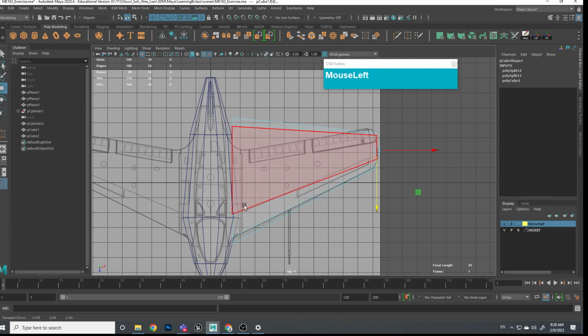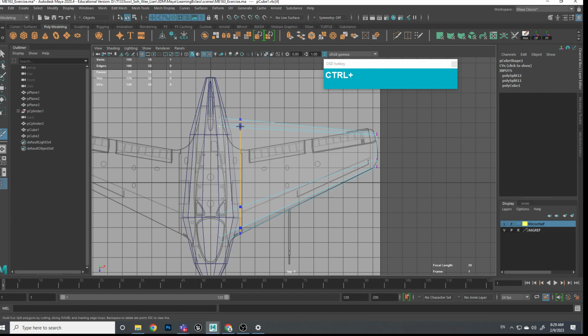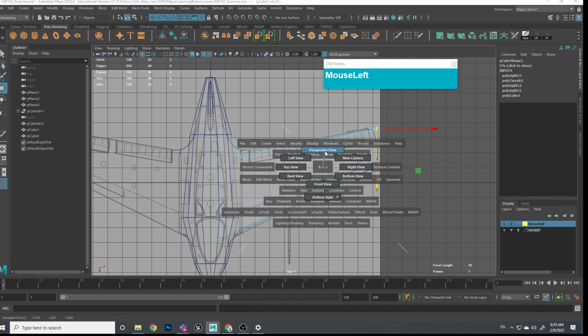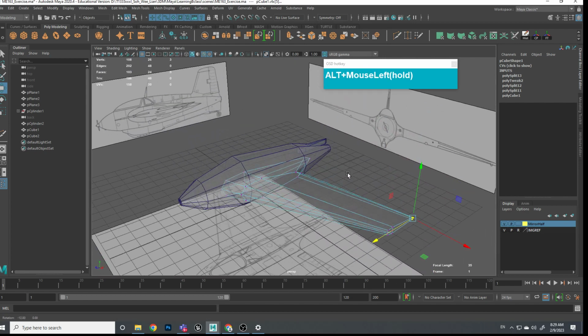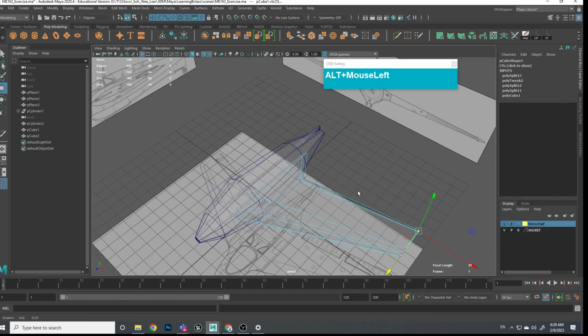What about this area here? We first move the root of the wing until it intersects the body, until it cuts into the body. Then we can insert one edge loop here, right where there's a transition, where there's this curve here. Press Q to select, grab this tail vertex section, press W, and then move it up here like that. I'm not even going to go into the subdivision mode because I know the subdivision is not going to look that great. Now we got one wing done.